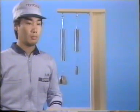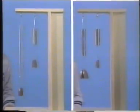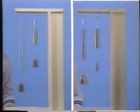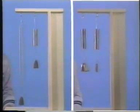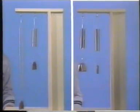You will notice that the lighter weight oscillates faster than the heavier weight. When you compare these vibrating systems, you will find that the frequency of the vibration varies depending on the strength of the spring and the heaviness of the weight. The frequency at which a particular system oscillates or vibrates is called the natural frequency of that system.